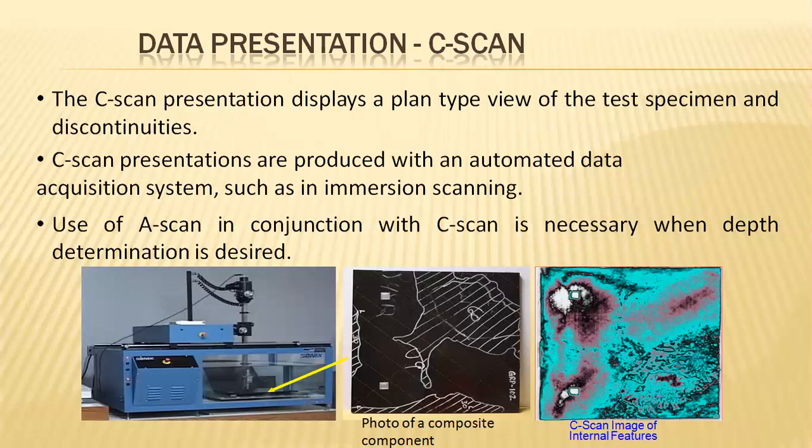So for the surface levels and the subsurface levels, the C scan representation, or utilization of this C scan processing with a lower frequency of sound waves, is nominally sufficient for observing the defects when the immersion technique is being utilized.